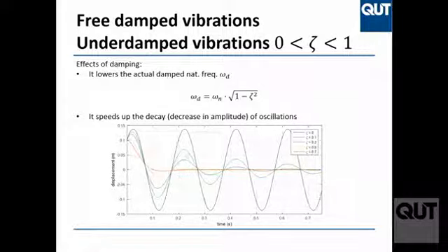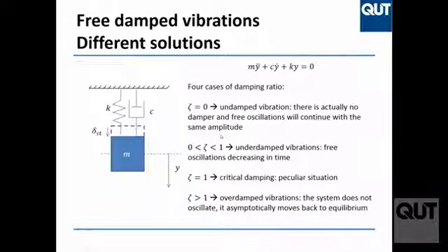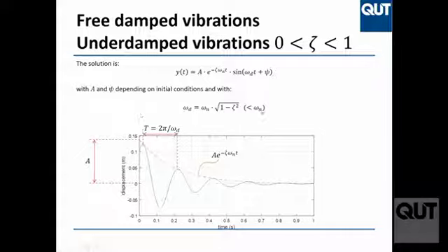Here, an example of the effect of omega d. So omega d is equal to omega n times that factor. What happens if I increase zeta, keeping omega n constant? How do I do that in a system? I have this system. I want to keep omega n, the undamped natural frequency, constant, and increase zeta of this system. What do I touch? C. I increase C, because if I increase C, omega n won't change.